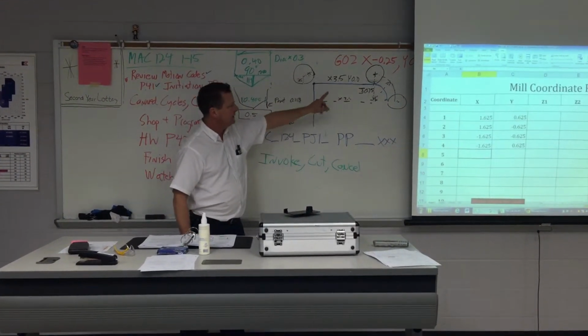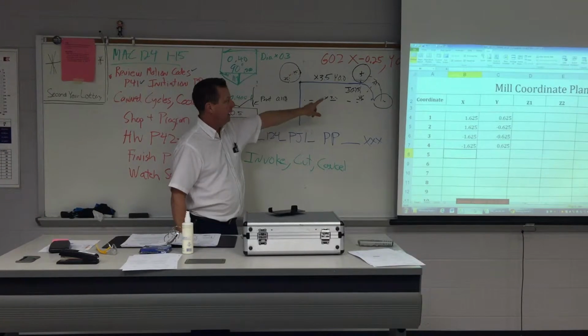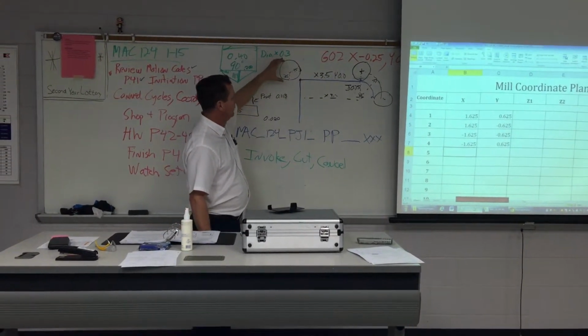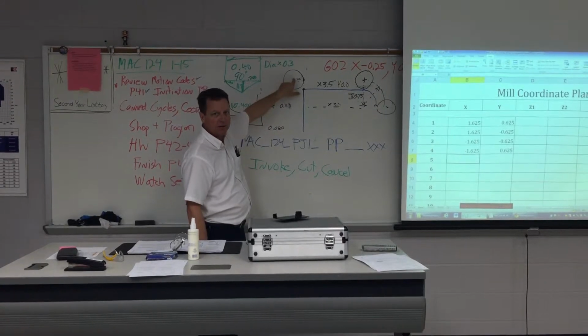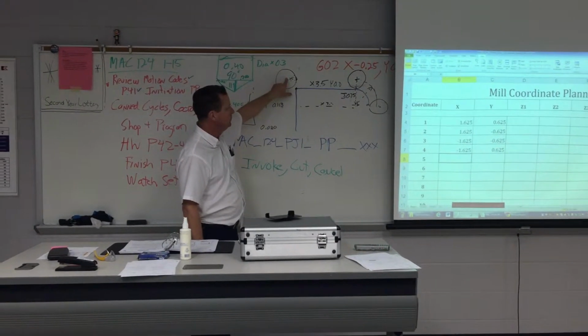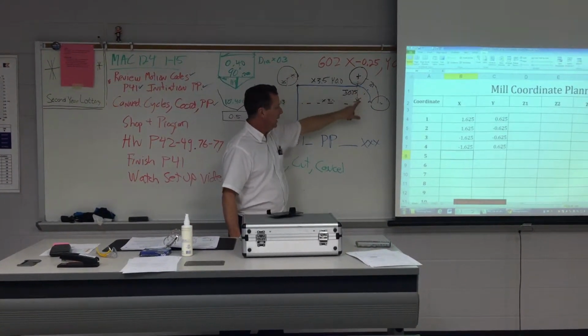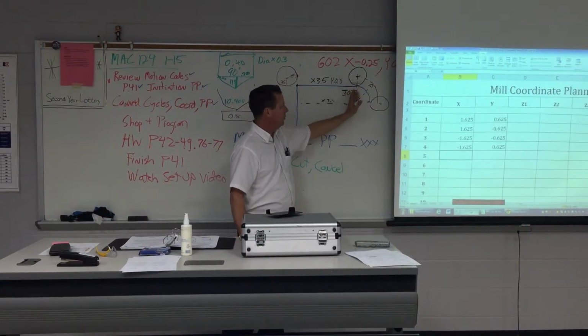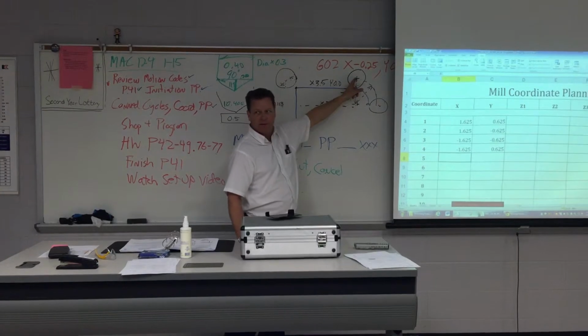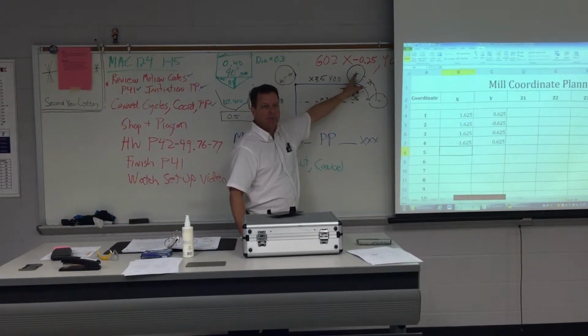We went over this extensively today. And in the case where we are not using cutter compensation but programming off the center line of the tool, we had to adjust the vector from being a 1/2 inch radius on the part to a 3/4 inch radius to the center line of the tool.